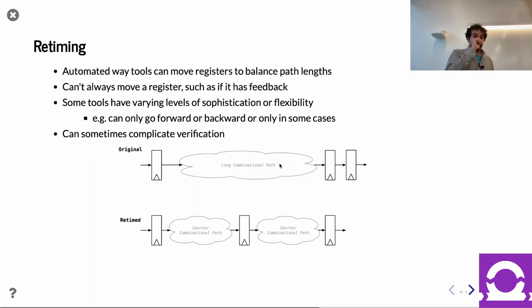Now, some of you may be familiar with something called HLS, or high-level synthesis. High-level synthesis is a hardware methodology where you describe, as the name says, higher-level semantics, the functional behavior, and let the tools do a lot of work. One of the things the tools will do is choose how much to pipeline things, how to block things, and that kind of stuff. In the spirit of making tools do the work, they choose pipeline depths at a high level. So humans aren't thinking about pipeline depths in that methodology. They're just thinking about function, but the tools think about pipeline depth.